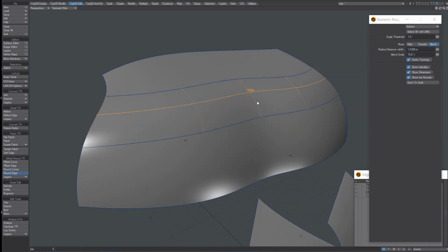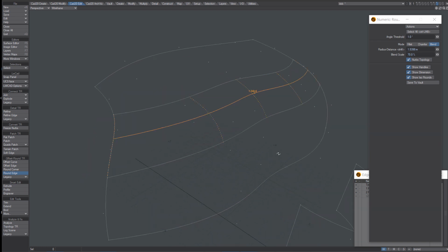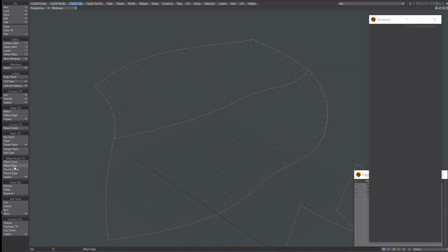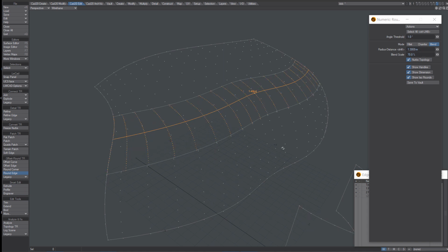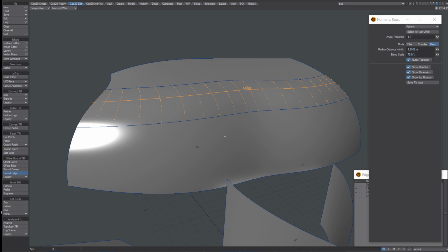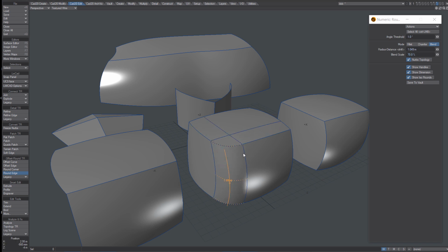We are rounding along each isopoint, and the side edge uses the offset edge routine. So we have a minimal count of control points, and if we need even higher precision, we can still refine the surface into more control points, and then when using round we have more isopoints, more rounds, and even higher precision. So now this rounding of NURBS surfaces works 100%, but simple NURBS surfaces have some limits. You are not able to create any shape with simple NURBS surfaces.